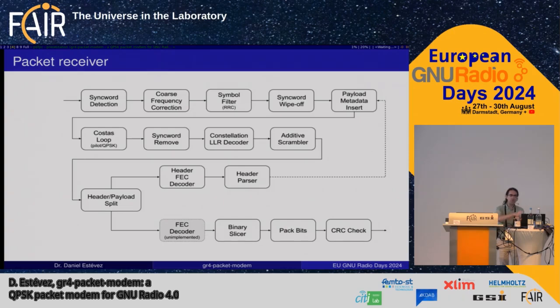64 QAM would be one constellation symbol coming in, 4 bits coming out, or 6 of them. So yeah, that kind of works with the current gr4 runtime. There are some rough spots just when the change happens, but it almost works. Then you need to descramble.